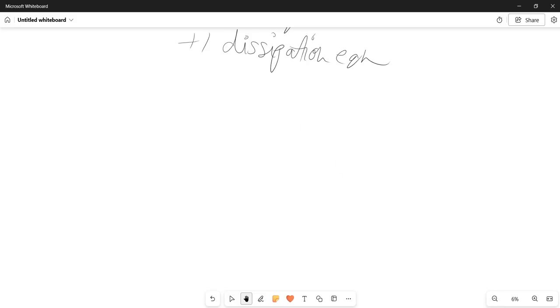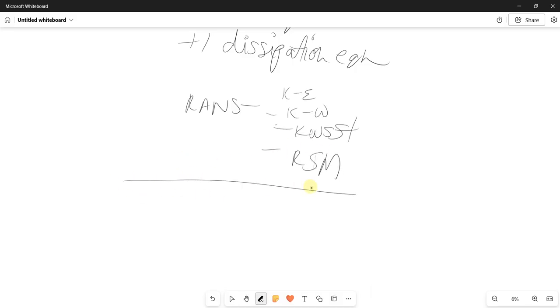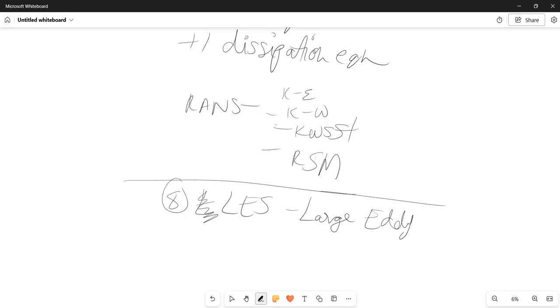So now we have completed RANS. We had K epsilon, K omega, then K omega SST, and then your Reynolds stress model, RSM. So we are done with RANS. Now we'll be jumping into the upper ones. So you have LES, which was number 8 if I'm not wrong. LES, large eddy simulation.